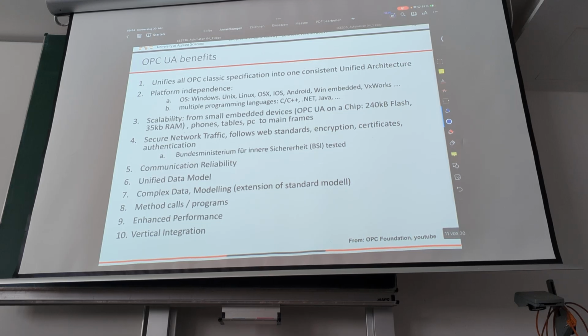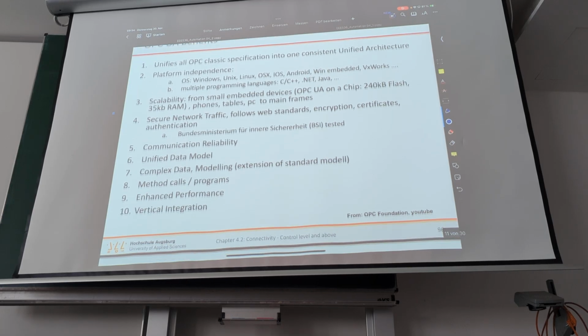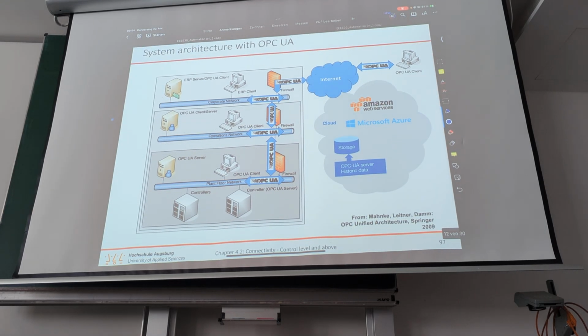What we used OPC for, for example, was that we had a simulation model of the whole plant, and then instead of connecting the DCS to physical hardware, you could connect it via OPC to your simulated system, and the performance was good enough for the system actually to work in real time. So it's really a performant way of communicating and what the industry in the end needed.